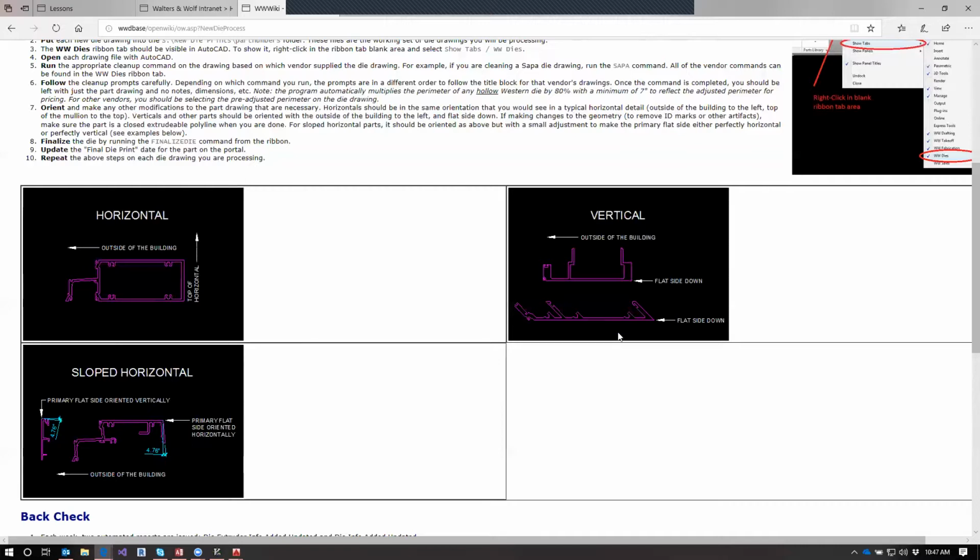When you tell the shop miter angles, you want to give them a miter angle that they can actually use on a table saw or a miter box. The only way they're going to be able to cut this part is by lying it on the flat face. So that's why our fabs are always lying on the flat face. Even this sloped extended cover has a flat face here, and that's probably what they're going to set on the table, so it's oriented vertically. Some flat face has to be oriented horizontally or vertically, and usually it's the biggest one.